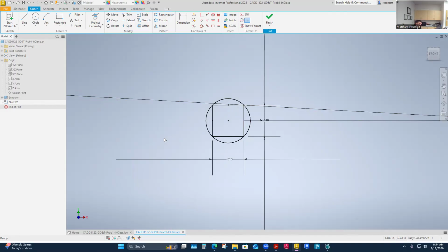GD&T can allow us to say, hey, locate that with a circular tolerance zone, not a rectangular tolerance zone, and we'll still call it within spec. It's really still picking up the same distance out from center as this one that was acceptable. This is an acceptable location for that circle to live in. So all of these around the circumference of the same circular tolerance zone would also be acceptable parts, because if this is acceptable from this far out, then this is absolutely acceptable around this.